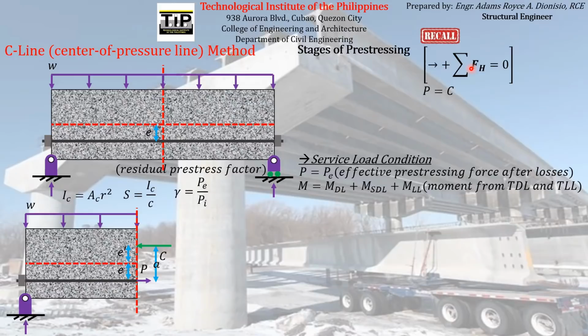Another thing from statics that we have to satisfy is that the moments acting on this particular left segment must also be balanced. Therefore, if we sum up all of the moments acting on this left segment, the summation of their moments must be equal to 0 in order to say that this left segment is in equilibrium. If the summation of moments is equal to 0, it means that there is no tendency to rotate at this particular segment of the concrete beam we are considering here.